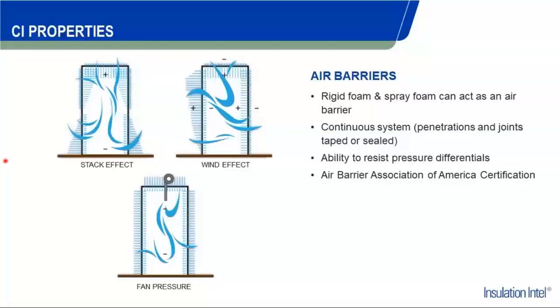One ideal approach is to consider using an air barrier on both the internal and external wall assemblies. But be very careful, make sure that one of those air barriers is vapor permeable so that you're allowing that wall system to dry as the moisture or the humidity levels change and move through the wall system. So it's extremely important. You don't want to create too closed a system where you have a moisture sandwich. You want to have one of those be permeable so it can dry out.